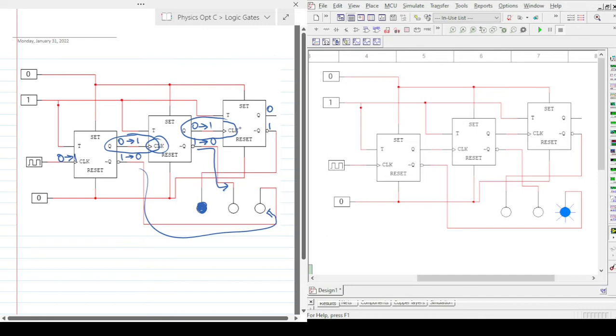So this clock also goes from 0 to 1, which means this goes from 0 to 1 and that goes from 1 to 0. So this LED would then turn off like that. That explains why, even though the software initialized all of them to be on, the next thing that happens is that all of them go to off. So that's the binary 000 that I had there.